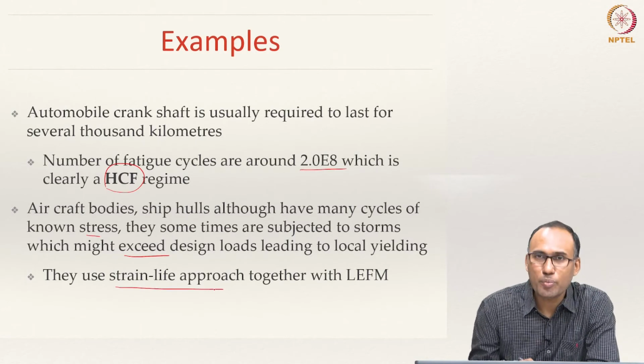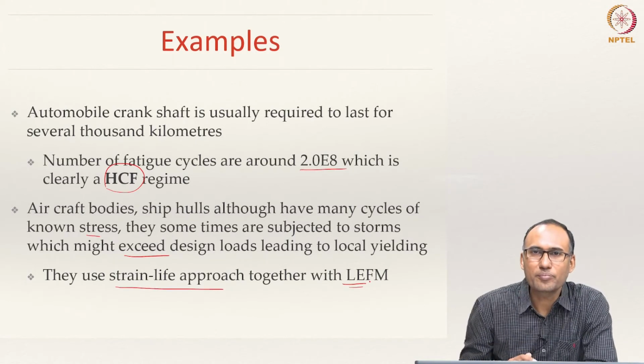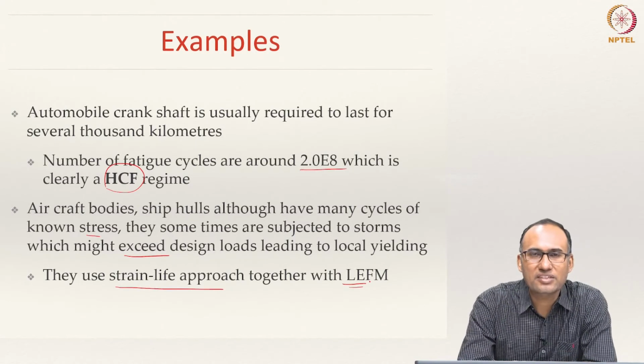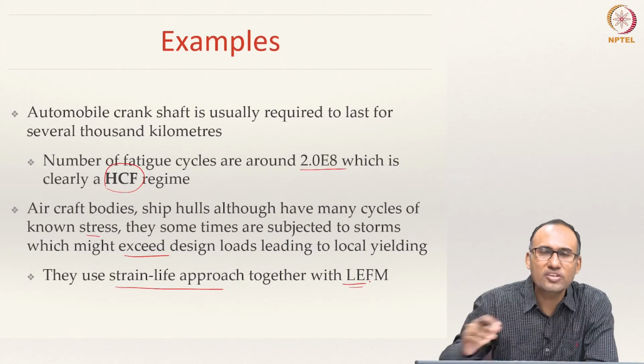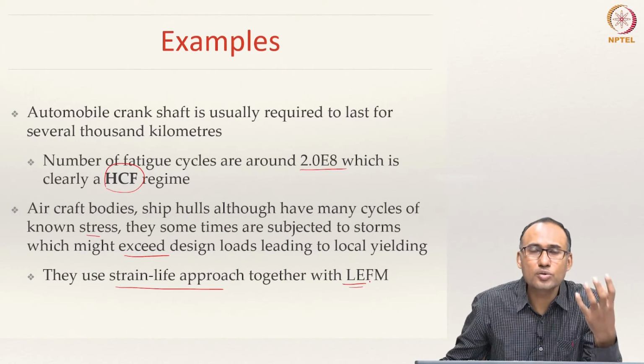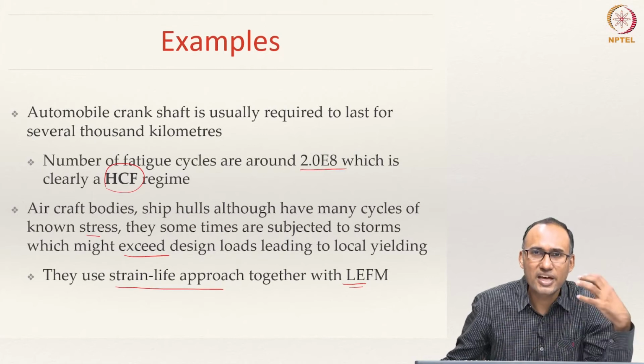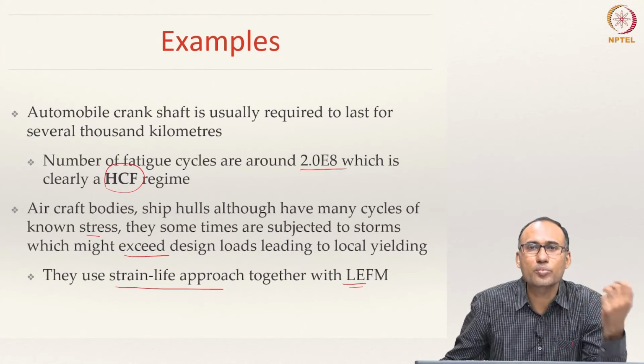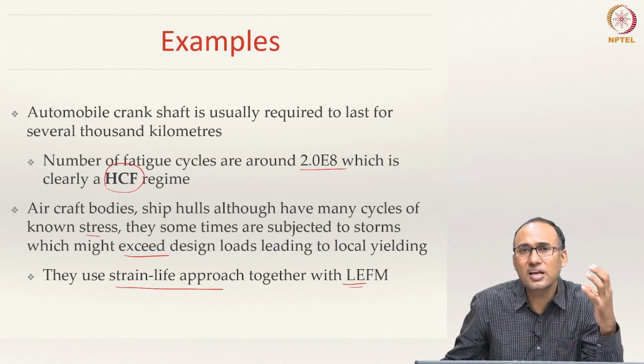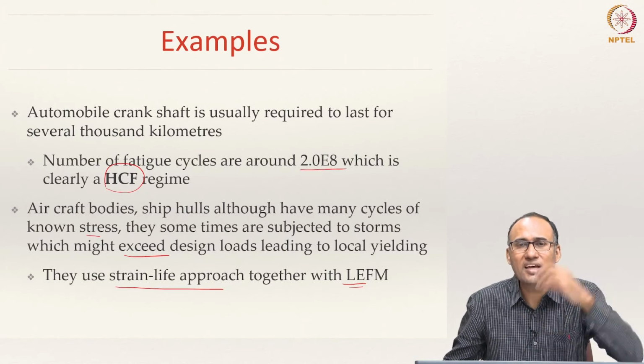Usually for the design of these components we use the strain life approach together with LEFM, the fracture mechanics approach, in order to design components such as aircraft bodies, ship hulls or nuclear reactor components and so on, which are critical and known to be subjected to very high stress levels.